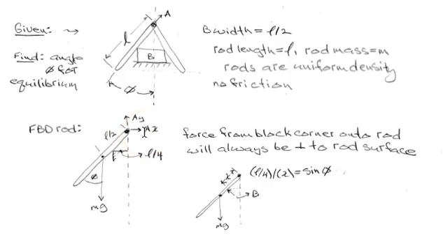Now this is the force of the pin on the rod. So the pin is pushing up and to the right. So obviously if we were to draw a free body diagram of the pin later on, if we were to happen to need that or to use it as a check, of course it would be experiencing an equal and opposite force from the rod, so it would feel the rod pushing down and to the left. So just a reminder. And then we see L over 2 here, this distance along the length of the rod to the point where we're going to apply the weight. So this is just a general sketch.